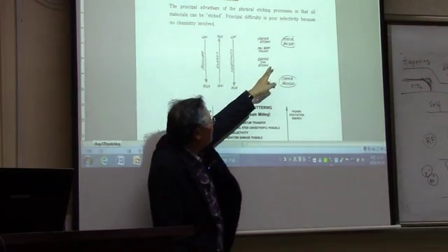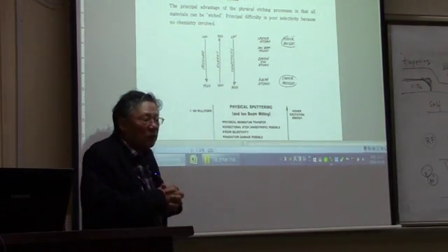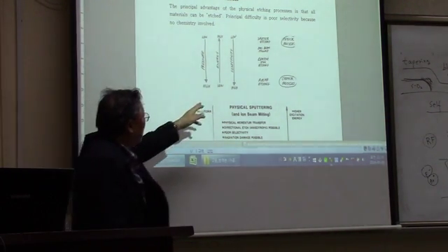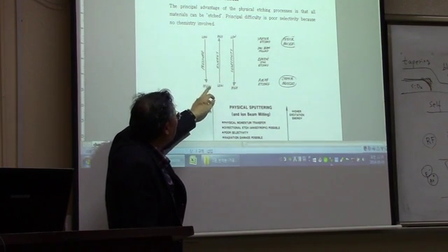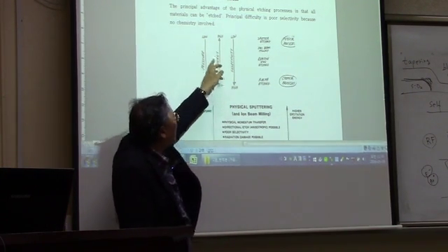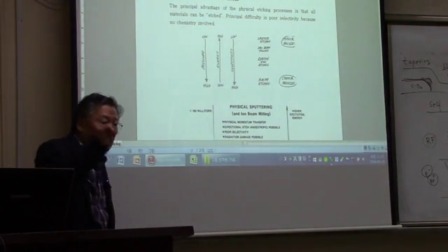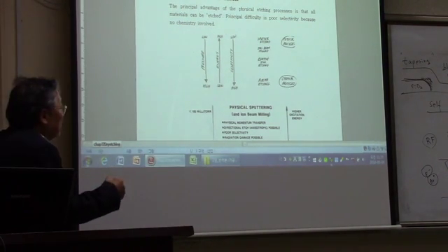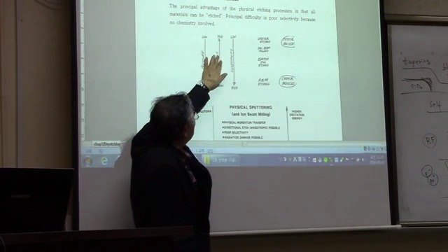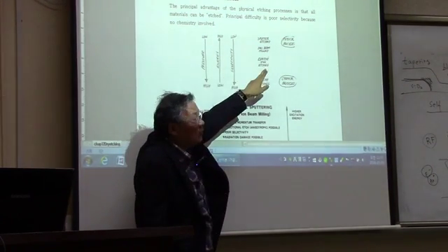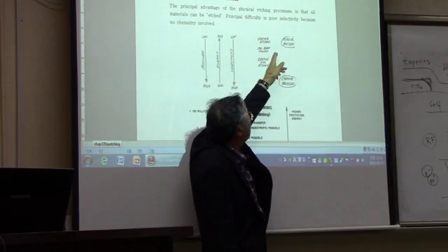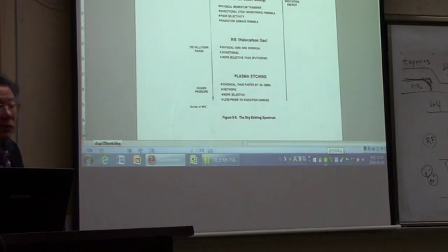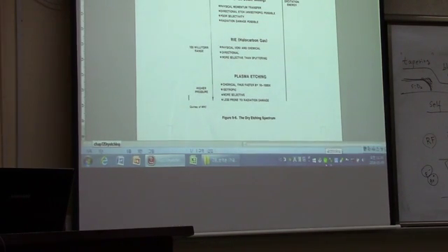That's why the equipment for the physical process is usually very expensive, because we have to keep a high vacuum. And we need high energies for the physical process, of course, because it has to accelerate the ions. So the energy should be high and the pressure should be low in the physical process. That's why physical processes are usually very expensive, but give very good dimensional control. Okay, this has been summarized.